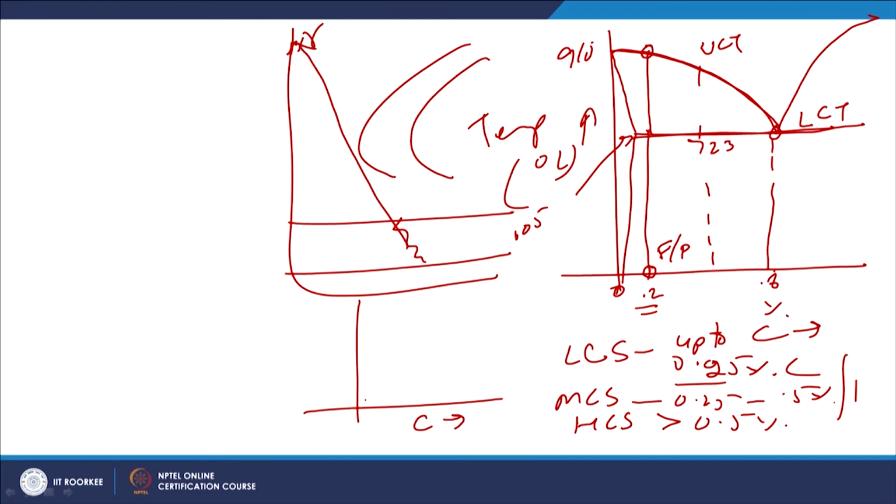If we draw the relationship between the hardness of the martensite and the carbon content, it is found to increase continuously, going up to 0.8%. So, high carbon martensite will be harder than low carbon martensite.